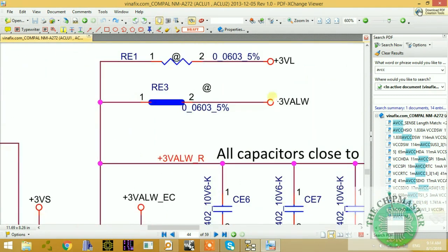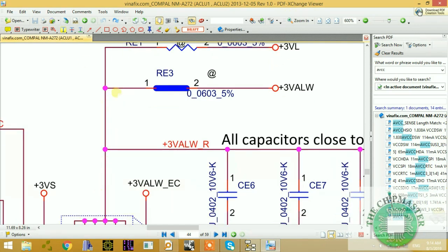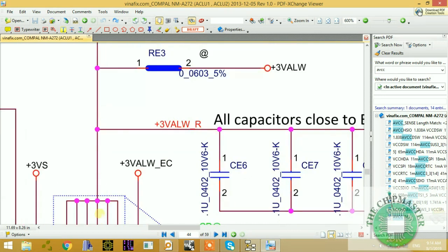It's 3 volts. See, 3 volt. This is a linear volt. We're going to get to this voltage shortly. As you can see, it's all combined and it's connected. Plus 3 volt always coming through a short connection. This is a short connection, right? It is just a pad. It's not a component, just a pad, and the trace is underneath it, and it's coming directly to these pins.